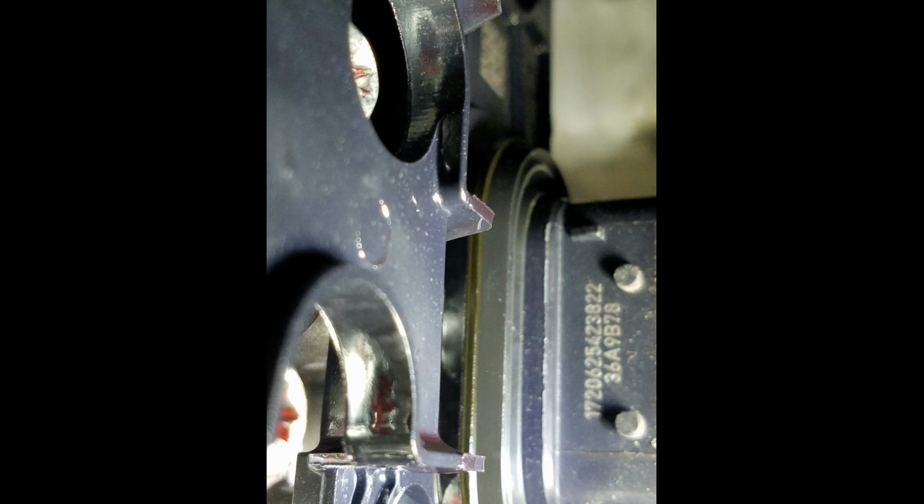I do find a corroded wire inside this connector after I've cut it open. Again, I did not get a picture of it. I guess you'll have to trust me. I fixed the wire. Actually, there were 2 or 3 wires in here that were corroded, so I fixed all 3 of them. Got it all wrapped back up, and my shift solenoid D code goes away. And I still have my harsh engagement.